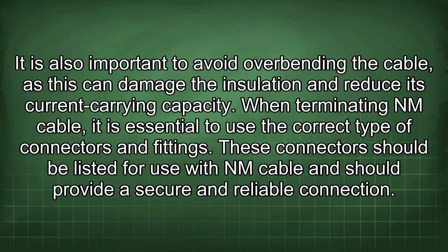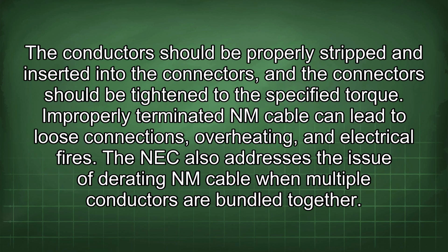When terminating NM cable, it is essential to use the correct type of connectors and fittings. These connectors should be listed for use with NM cable and should provide a secure and reliable connection. The conductors should be properly stripped and inserted into the connectors, and the connectors should be tightened to the specified torque. Improperly terminated NM cable can lead to loose connections, overheating, and electrical fires.